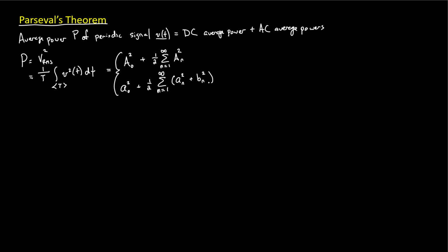So this RMS thing, I want to just point out, where is this coming from? This seems a little bit like magic at first. This is not magic. This is just a result that it's the same thing as VRMS times IRMS times cosine of theta V minus theta I. And that's what we remembered from the last board. And if we're doing it through a 1 ohm resistor, then our current is the exact same thing as our voltage, and they'll be in phase, so this goes to 1, and that's where our VRMS squared value comes in.